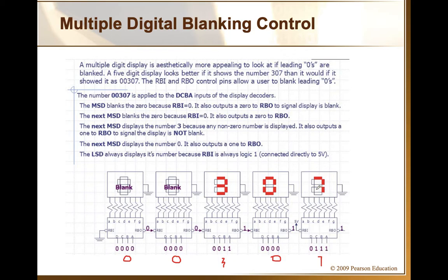I think what they've tried to do is that here, in any case, they have disabled this RBI, because they don't want that, if it's only one 0, it should not be displayed. Basically, for the last 7 segment display, they have disabled the RBI, so that no matter what, if it is 0 or whatever, it should be displayed, because normally we enable RBI so that the leading and trailing zeros should not be displayed. Now RBO is 1 again, and that's about it.